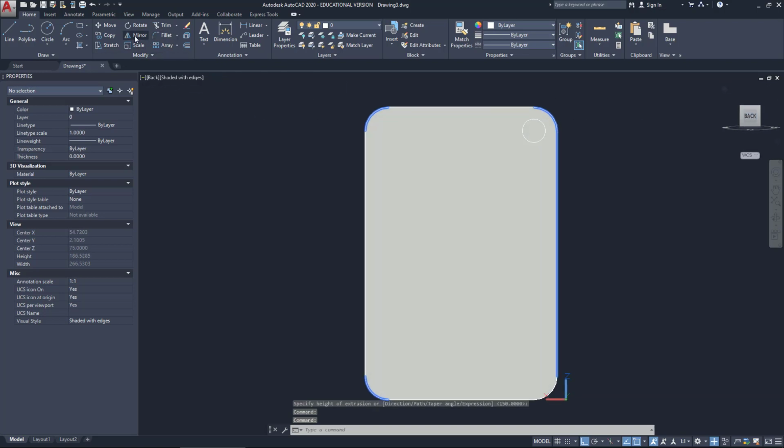I want to mirror if I can. So my mirror tool, this is my object to mirror, enter. First point on my mirror plane wants to be the top center there, center. Come down here to the center, click, and enter. Now let's enter again because I want to copy that object and that object.